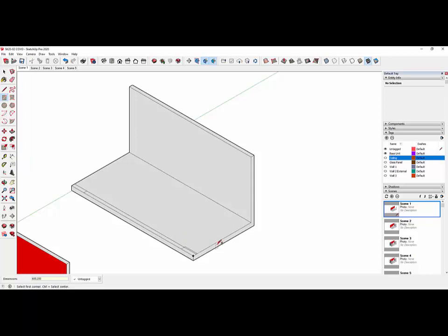And then we can go to the extrude tool. If you make a mistake, just simply go back and use the back arrow, put in the coordinates again, and then use the extrude tool. We can delete the line, and pull to create the height of our wall, in this case 2800. And likewise we could do the same with the opposite wall.